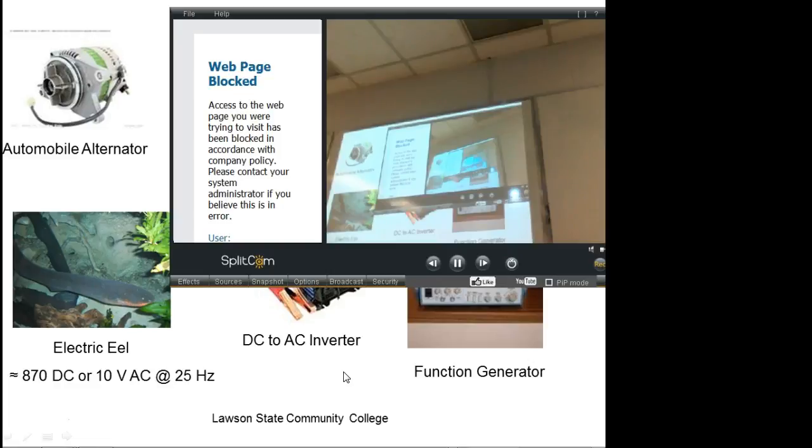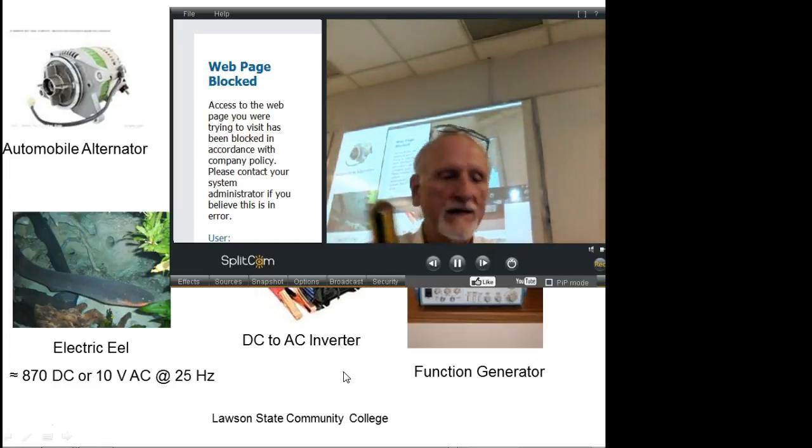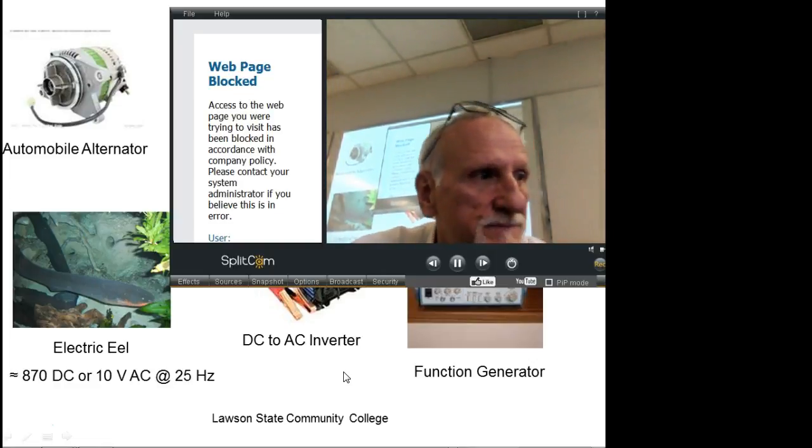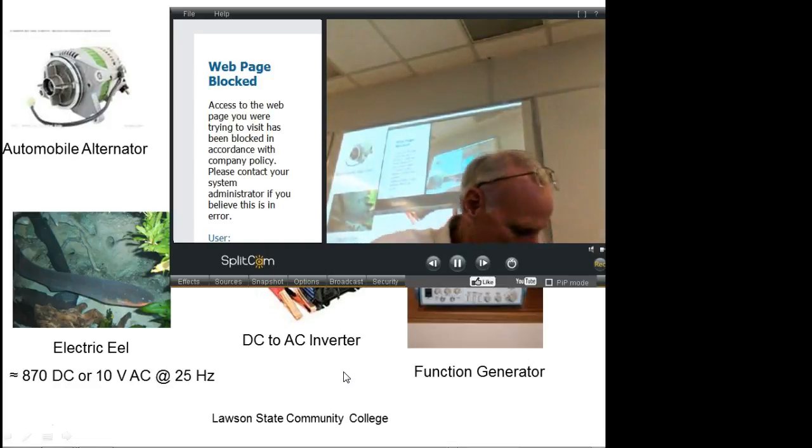With this wire, you can strip it with a cigarette lighter. It's a very, very thin insulation. So when we use this stuff, we really have to clamp it down, especially if we use it in AC, because AC constantly tries to create vibration, and it'll wear that insulation off. So this is not a real good example of an electromagnet. I hope I can get enough current in it to make it work. I know it's not going to pick up that.